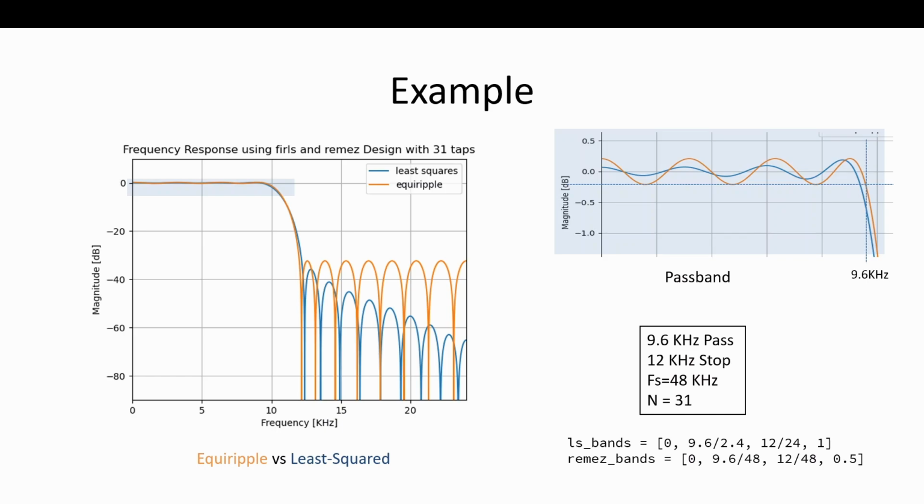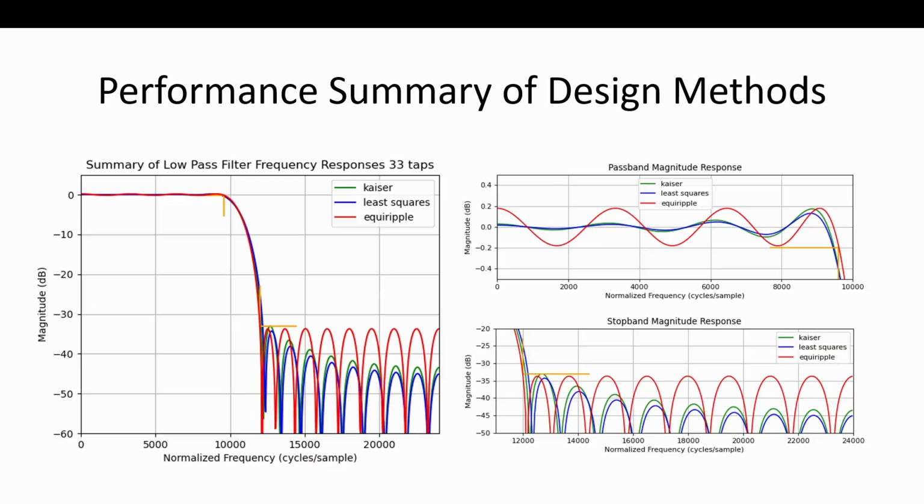And then when we start windowing, now it's no longer 1 over n, but it's like maybe 1.5 or 2 times that. But that's the trade you want to make because of the way we can attenuate the stop band. Make your filters twice as long, and then window, and you get a great filter, right? But does that make sense? Yeah, ultimately, when you're concerned about how tight can we resolve in frequency, can't get away from it being how long are you observing. And if you're observing something, is it stationary for that long time to be able to just keep up with that? So all those things come into play when you start getting into this.